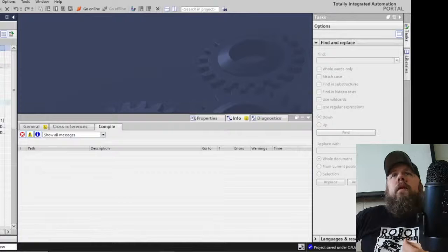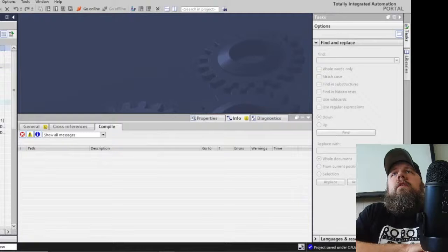Like where we might not have a differential pressure transmitter on hand, or you might not at the house, the ESP32 will mimic that. And instead of having to spend $400 on a sensor, we can get cheap, like $10 sensors and communicate with the ESP32, which then communicates with the PLC. So to the PLC, it just looks like that sensor.